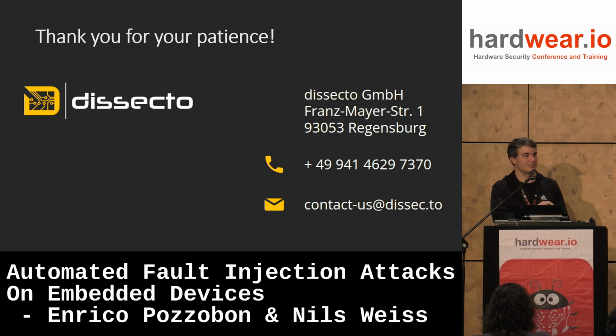So if you have a record that censors JTAG, which was already there in the MCU, you can add a new record that uncensors JTAG, and the last written record always has priority. In this case, it was possible to re-enable it. That is processor dependent, because on other processors this is not the case. There are ways to permanently censor JTAG.